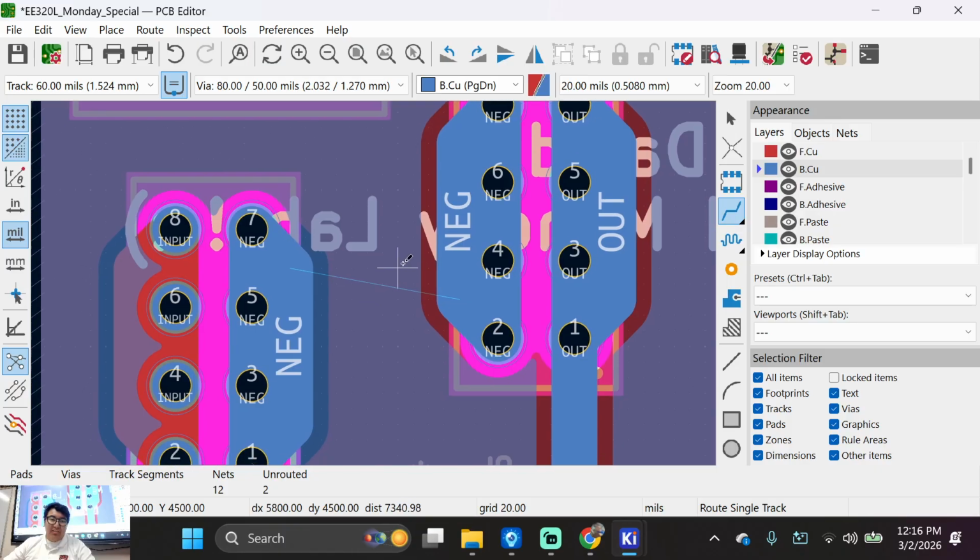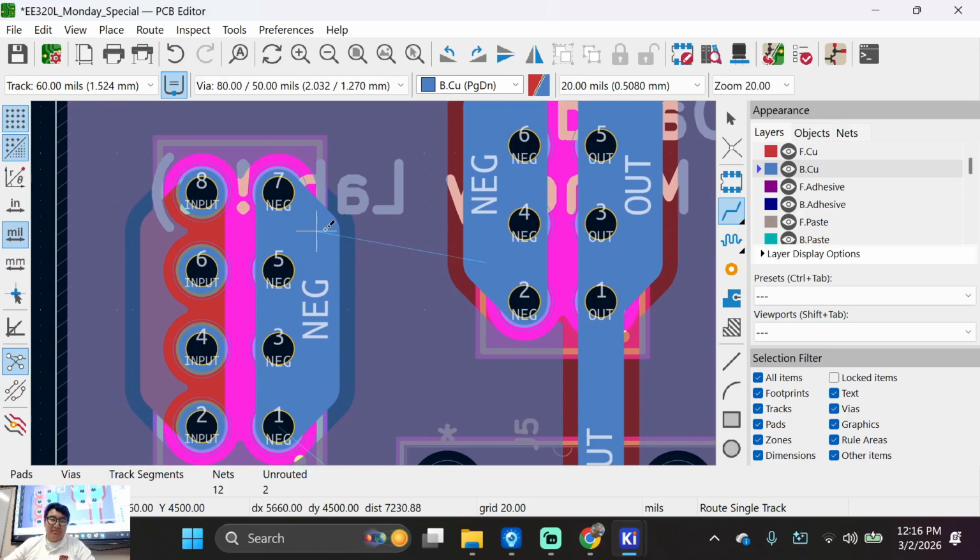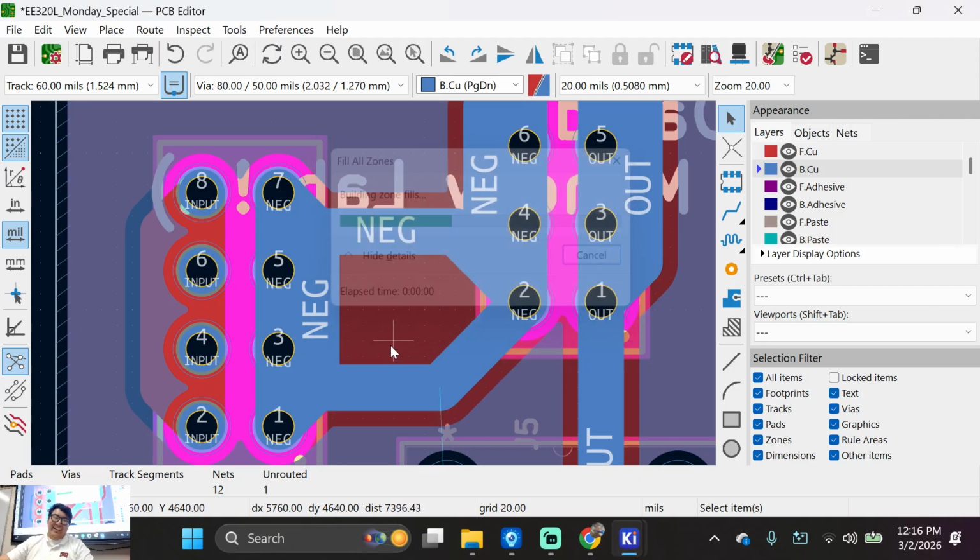And then what am I going to do to these two negative terminals? Connect them. Let me see if I can do something funny. I don't like this, because this is going to create an antenna. I can see it. This is an antenna, so noise is going to go through this. Remember Ampere's law? Yeah, this is an antenna. Do I like that?